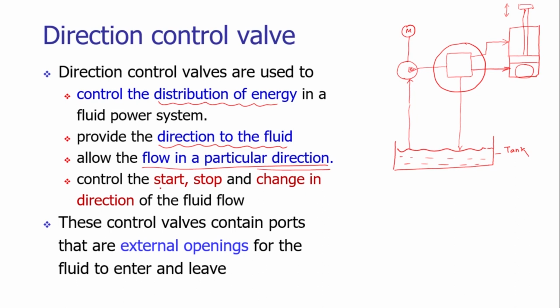The control valves are starting, stopping and changing the direction of the fluid flow inside the system. These control valves have external openings. It has an external opening here to get the fluid inside. It has another external opening to return the used hydraulic fluid. So external openings are there for the fluid to enter and leave the direction control valve.